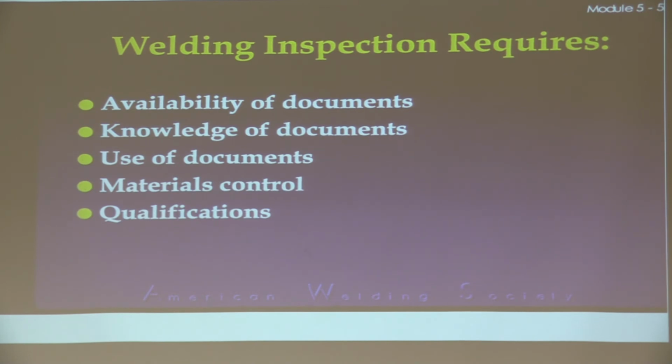Move over to the right-hand column of that page. First paragraph down, starts out, virtually all welder qualification test specimens are generally categorized as soundness tests, including bend test, nick break test, and fillet break test. The bottom of that paragraph, 3 sentences up, says for pipe coupons welded in the 5G and 6G position, specimens are removed in relation to the top of the pipe during actual welding. That's what I mean by, you need to make sure that you're on the top section, moving around.